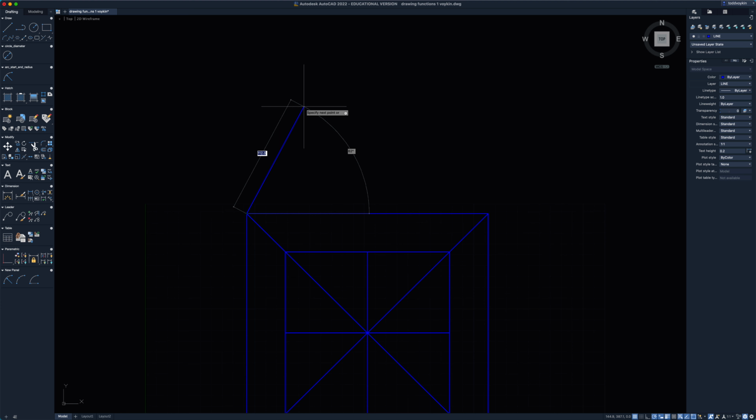So to ensure that I'm at exactly 62 degrees, you want to press the tab button, which brings that highlight over to the angle section right there, and I'm going to type in 62, and hit tab again, and you can see that locked it in at 62. And it tells me to make this line at a length of 100 and hit enter.